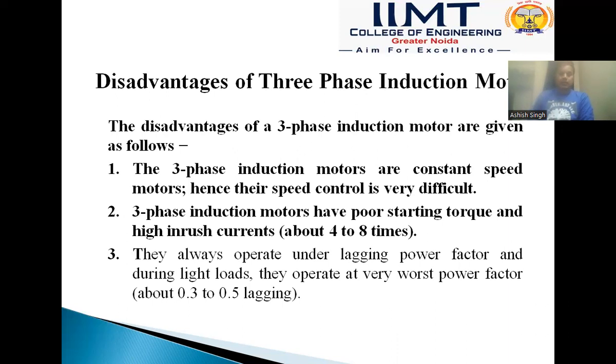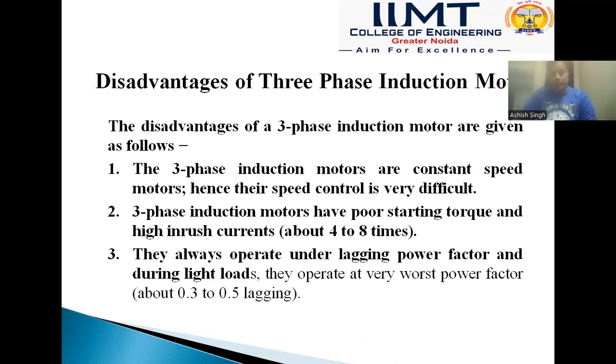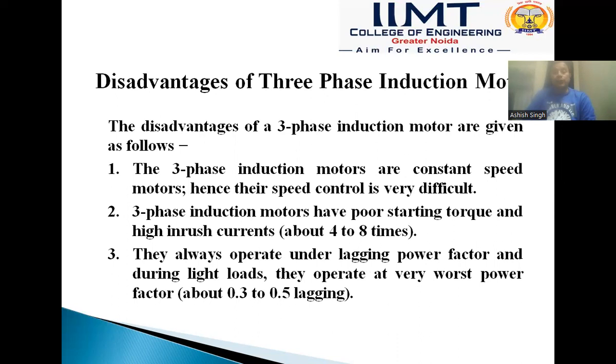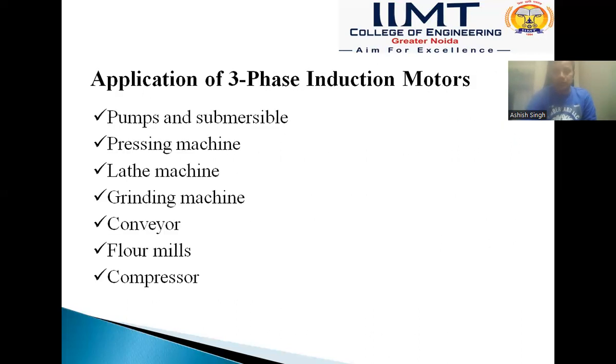Another disadvantage is that they always operate at lagging power factor, and during light loads they operate at a very poor power factor, about 0.3 to 0.5. These are the disadvantages of the three-phase induction motor.